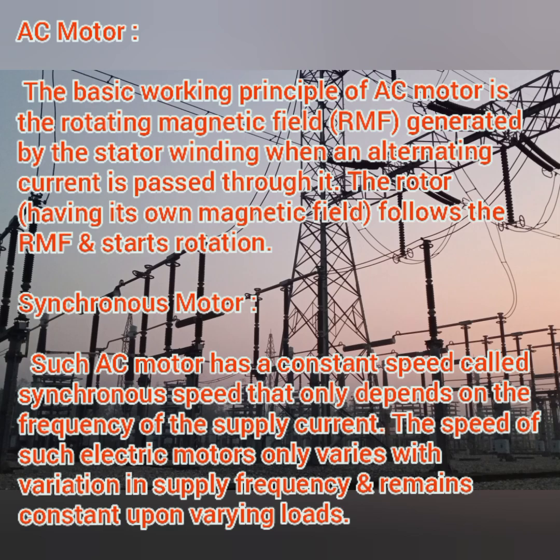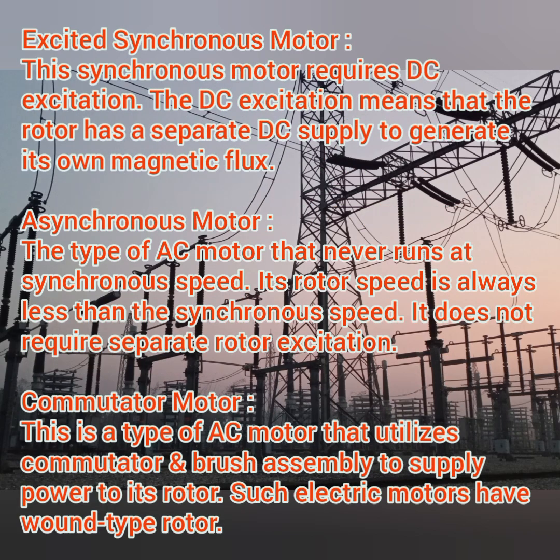So in here the synchronous motor, the motor has a constant speed, and the speed can be varied with the frequency of your current, but anyhow the speed will not vary with your load variations.